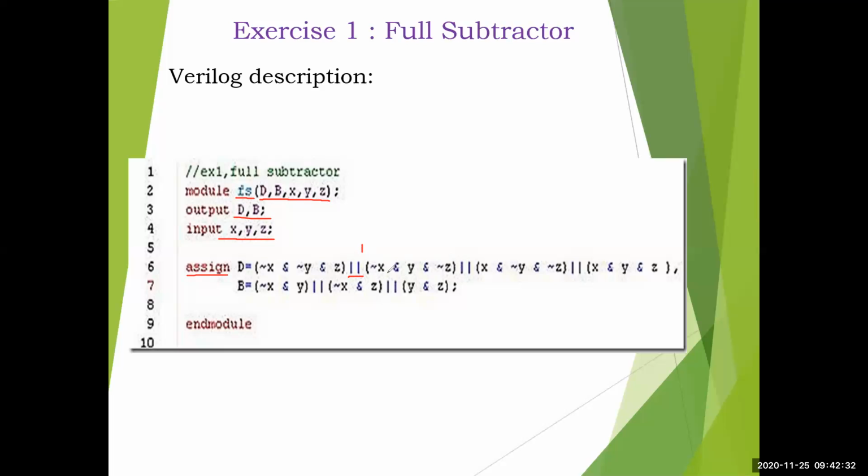Then not of x and y and not of z. The second term you had was x bar, y, z bar, so that is written here. Then x, y bar, z bar was there, so that is written like this. And then x, y, z. Then with respect to borrow, you had x bar y, x bar z, and yz. If you write the K-map, you are not going to be wrong, right? Simple, right? We have just replaced with the operators, so this now becomes the data flow description. Finally, our endmodule. Hope it is clear. Nothing much to do: if you have done this expression part clearly, it is not a big issue.